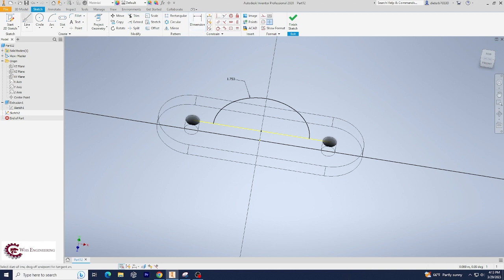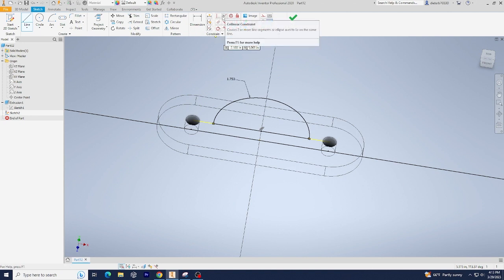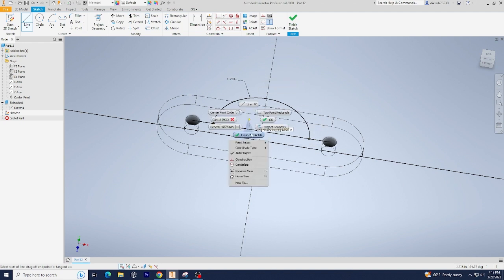Now we're going to select the line command because, as I've mentioned to you guys, we have to have a closed item or a closed part in order to be able to extrude it. You cannot extrude it if it is not closed. So this is now closed. And it's also the coincident constraint up here if you want to do that. Got to find the coincident. There it is, the coincident one, to make it work right. But anyway, all right, so now we're going to right-click and say Finish 2D Sketch.